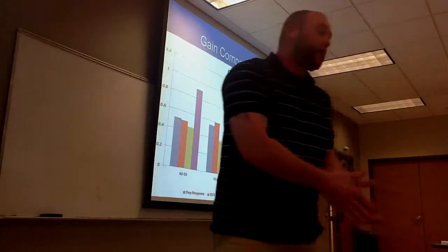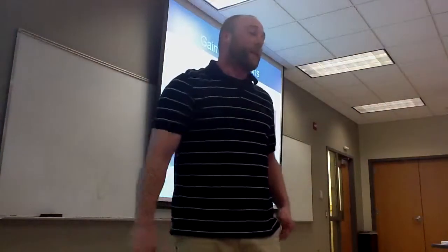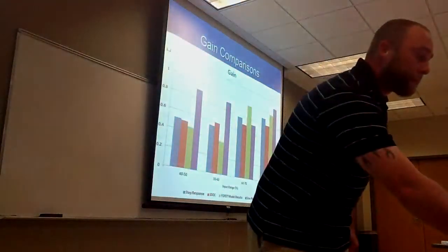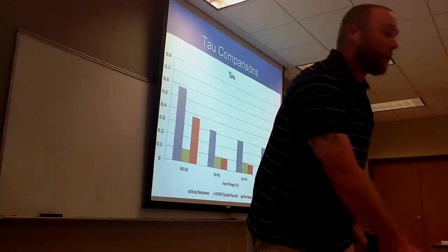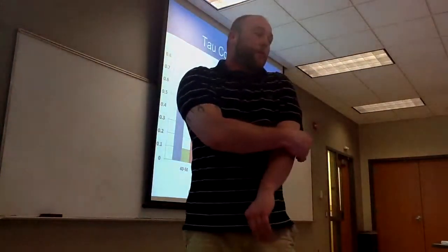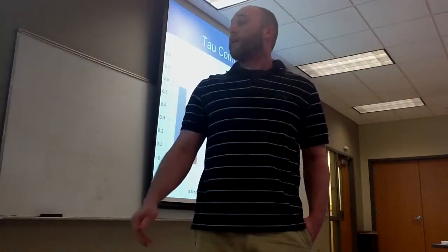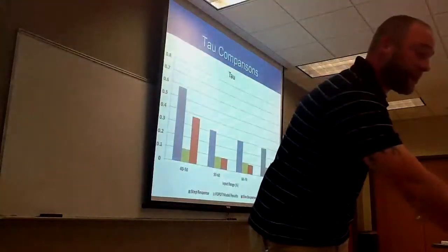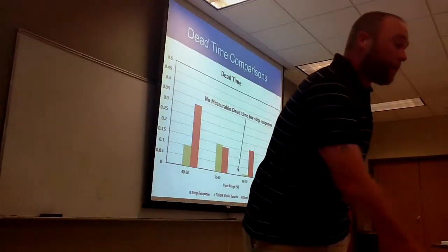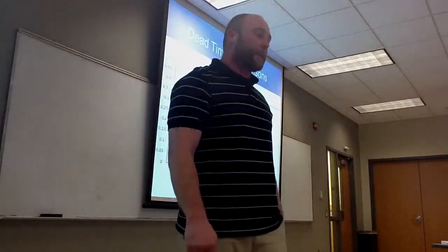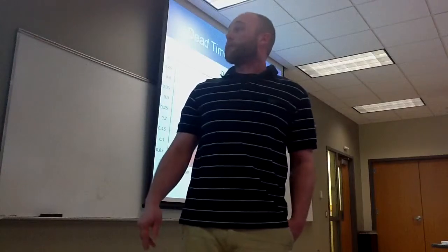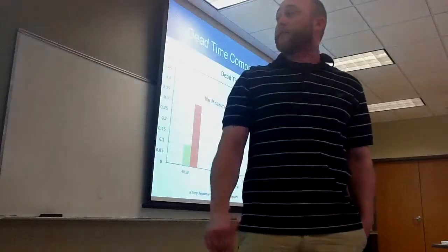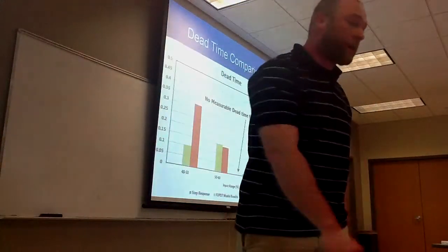Here's a comparison of our gains for our step response, our SSOC, our FOPDT modeling results, and our sine response. Our tau comparisons, other than 40 to 50, all seem to be pretty much the same. Our step response dead time was pretty much unmeasurable for our comparisons, but as far as our sine function and our FOPDT models,